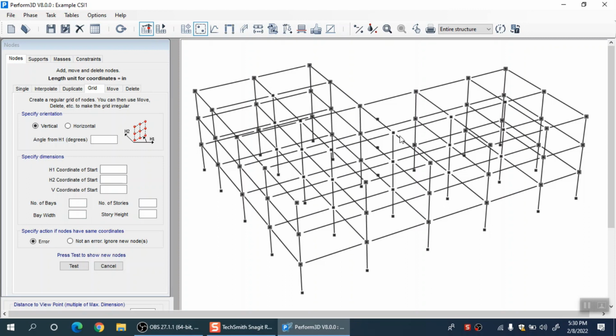So, if a particular beam in this model experiences a moment more than the yield capacity of that beam, the program will tell, right. It will not follow F equals k u forever. It has that feature in this model that it will tell the actual damage. If a connection experiences forces which are more than its capacities, the program will tell. The capacities are already incorporated in this model. Similarly for columns, since it is a steel frame building, columns, beams and beam column connections, these three elements are modeled as nonlinear elements.